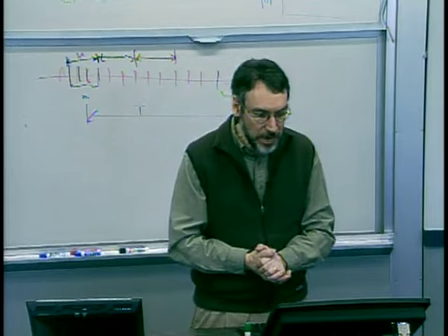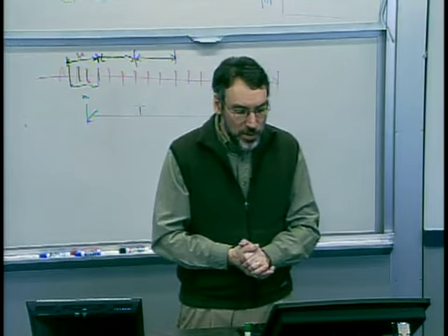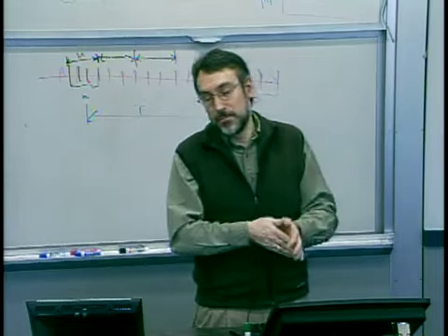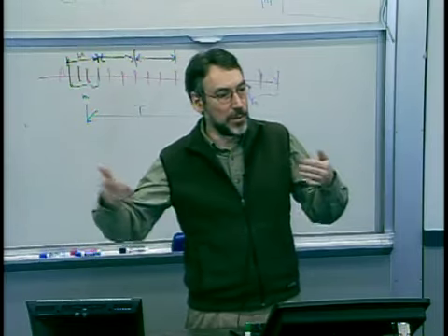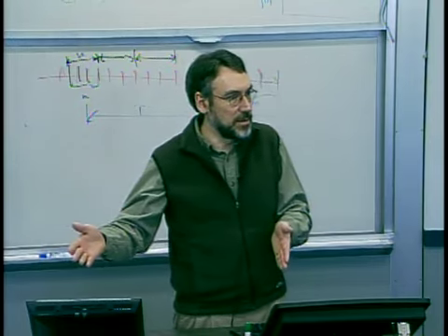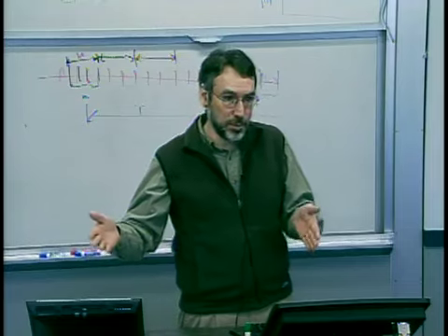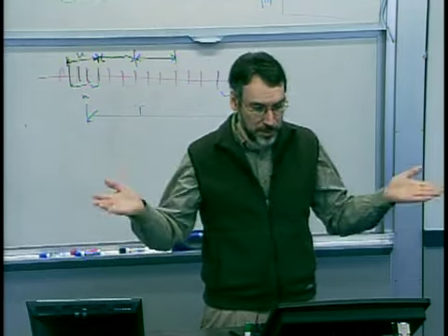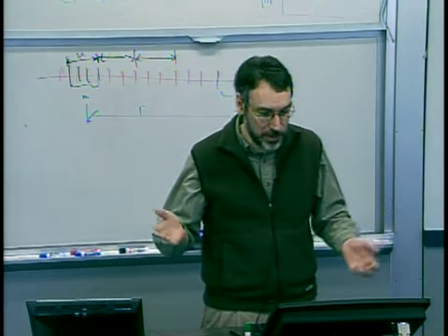And the point here is that once we've got a distribution like this, based on historical data that we use to build our control chart, we basically have a model of our process, right? It's a very simple statistical model that says it has a particular mean and a particular variance in the normal distribution case.